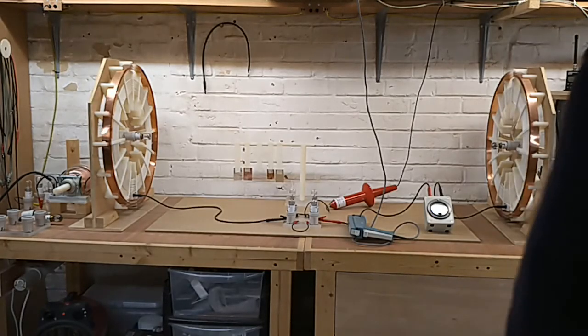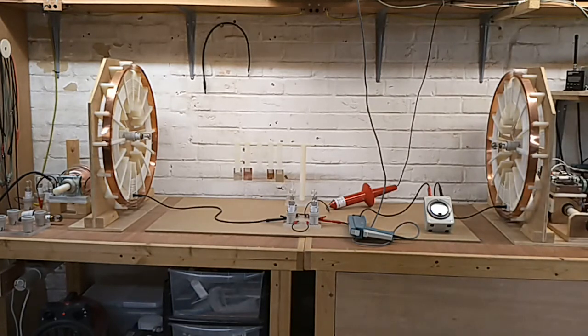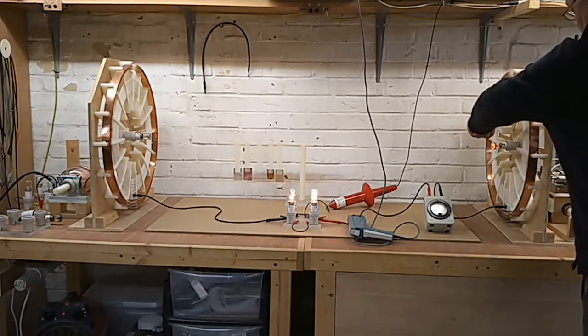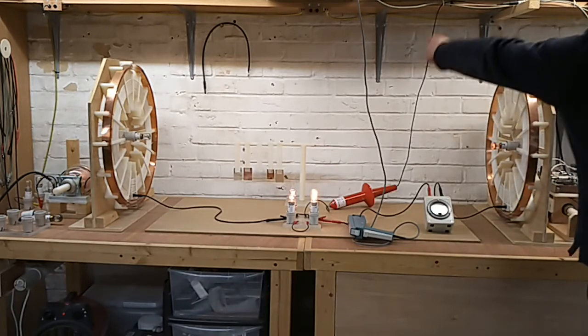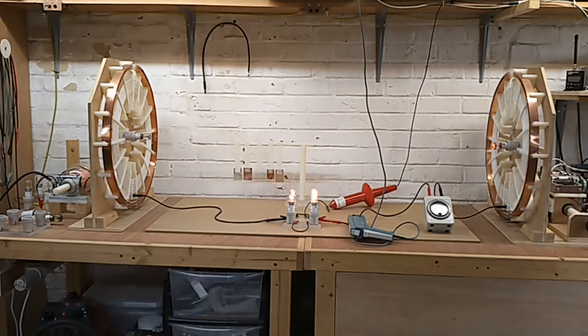Okay, so now we're going to have a look at the actual experiment running itself. I've reconnected the generator, removed the vector network analyzer, and now I'm just going to run again. So it's about 300 watts, as before, 4 amps primary current and around about 150 amps. There's probably a fair bit of tension on here. Yeah, there is discharges coming out of the top there.